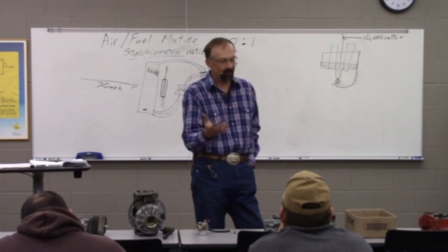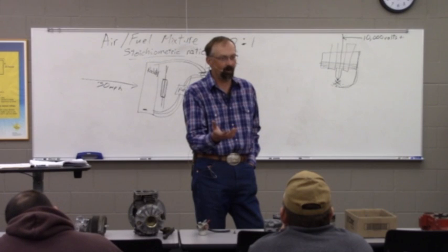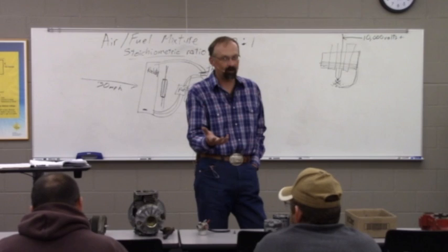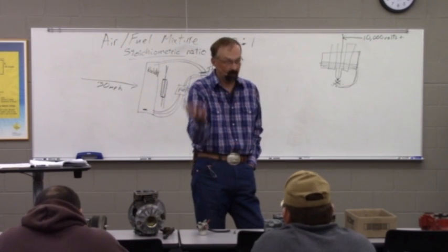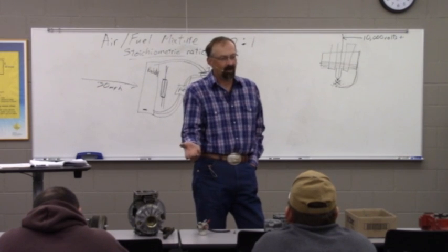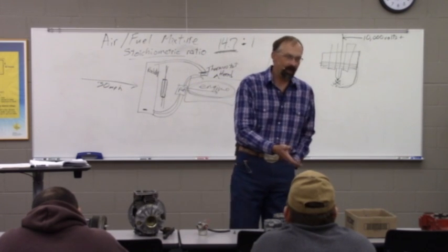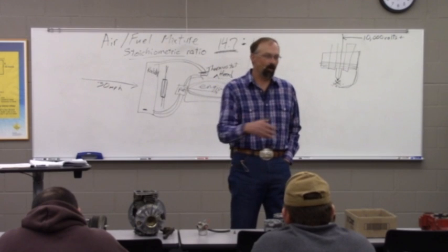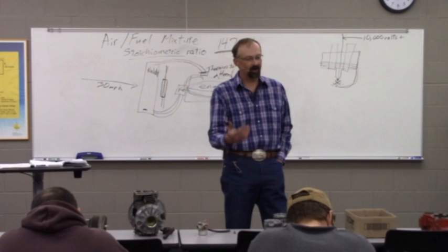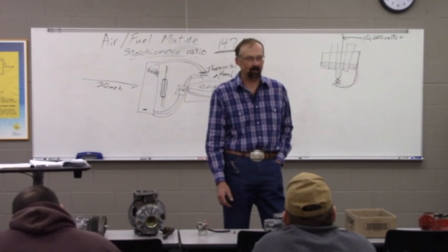But on the engines that run that exhaust gas recirculation, you're seeing so much higher temperatures that, because of the temperature, a lot of the manufacturers are specifying the synthetic, and I go with that specification. On the engines that don't have that exhaust gas recirculation, where you don't wind up with those excessive high temperatures, we're really not seeing a lot of advantage to the synthetic motor oils.